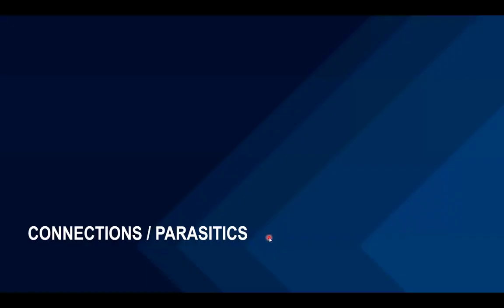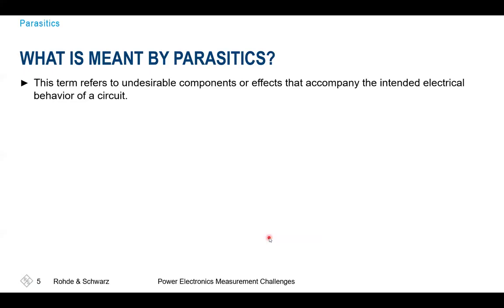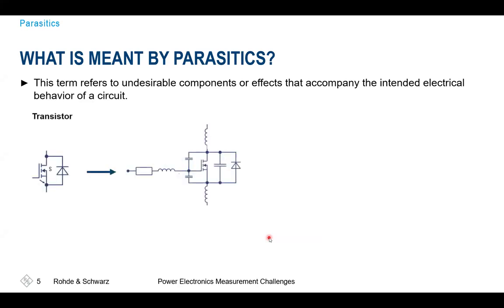What's important to keep in mind when you're switching to a semiconductor with a faster switching inside, you'll have a wider induced spectra there, and thus you might have to consider more effects on your circuitry than ever before. From the transistor itself, it's not only that you'll have the transistor inside, this transistor also has to be connected to the package.